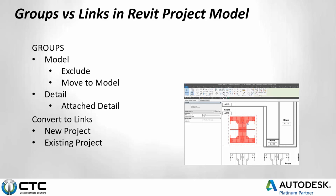And then we'll talk about the details of putting in the dimensions on these. Detail groups can be used in two manners. You can create a detail group that is simply documentation objects. Maybe you're doing a drafting view or detailing a section and you want to use that detail later in another view. Without redrawing it, you can group those details and then put those details in another view so that you can use the exact same detail without having to remake it or copy paste it over. And then if you edit one detail, it updates the others. And the other difference is attached detail group.